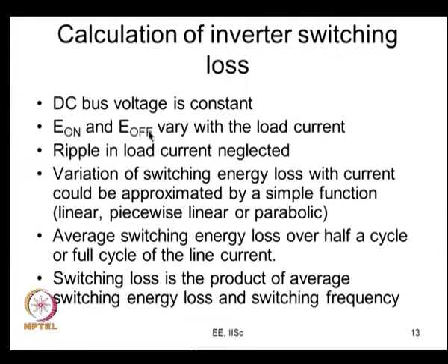Then you have this E on and E off, which are available in the data sheets, and sometimes they could have been measured, as I was just talking to you a while back. So, these E on and E off vary with the load current, roughly proportional to the load current.